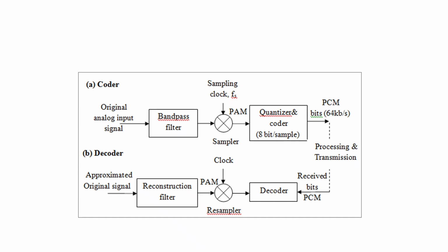It consists of the transmitter, receiver, as well as channel. First of all, the signal will be an analog signal. The signal is generated from the source and converted from a physical quantity into electrical form, in analog format, and is made to pass through a band pass filter. This band pass filter has a particular band of frequencies; the signal in that band is allowed to transmit and the other signals are eliminated. Because of that, the effects of noise added in the system are reduced.